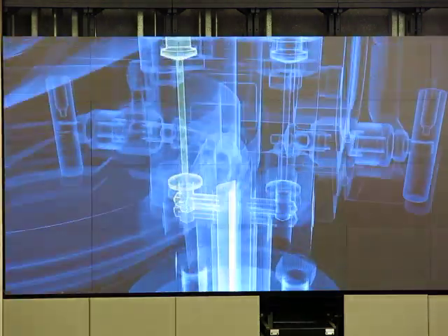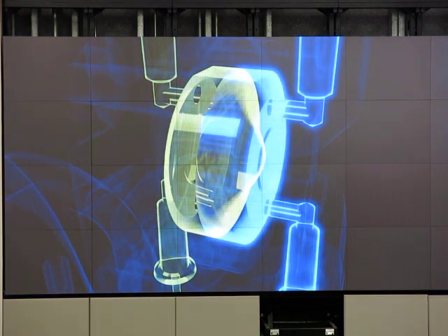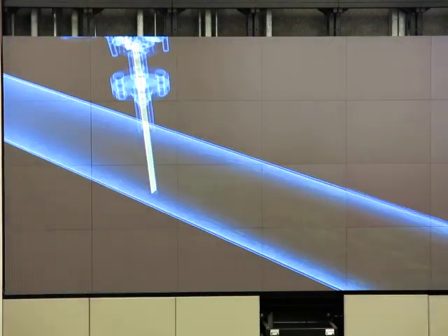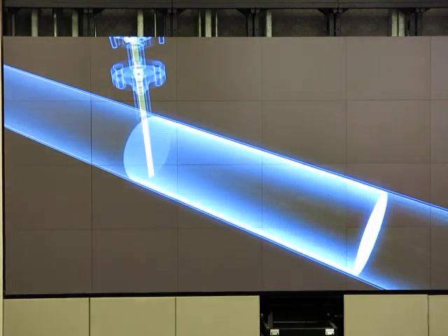As soon as the fluid starts to flow, an additional impact pressure against the front of the probe is generated, also known as the dynamic pressure. On the rear of the probe, in contrast, only the static pressure, which is not related to the flow, is still measured. As a result, different values are detected in the pressure chambers of the sensor. Higher pressure against the flow and constant pressure on the rear of the Pitot tube. This pressure difference is a direct measure for the flow velocity and thus the mass and volume flow in the pipe.